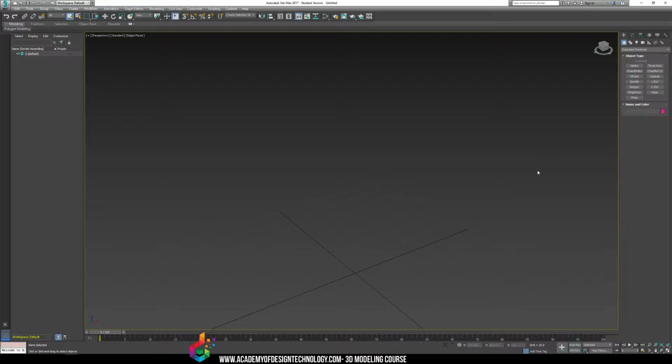The better the base shape that matches exactly what you're trying to do, and then going into Edit Poly, the easier it will be for you to work with and to modify different objects. That includes anything inside this menu. Things like stairs, doors, windows, standard, extended primitives. I would just suggest for now to play around in standard and extended primitives and use them as a base before you add edit poly. So just try and get something that matches your shape close, and then we can play around with different object modes.